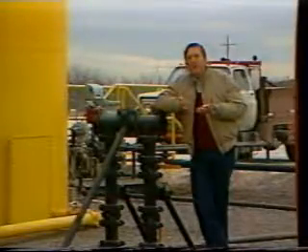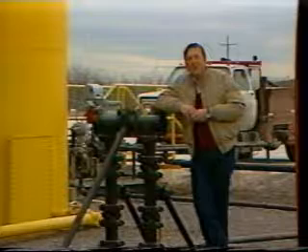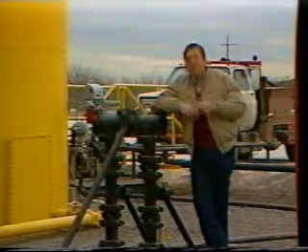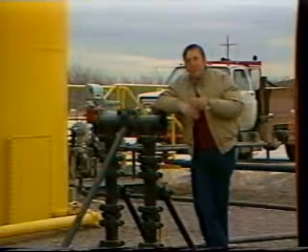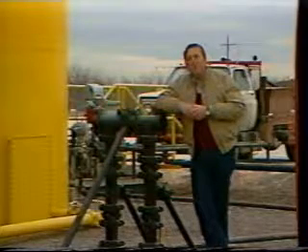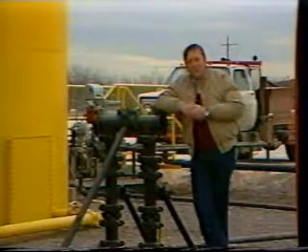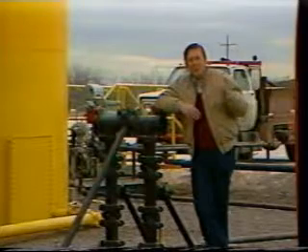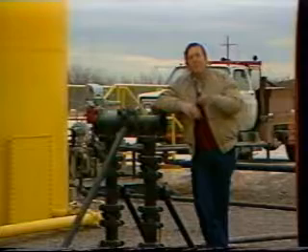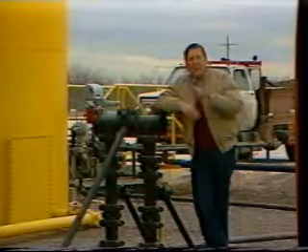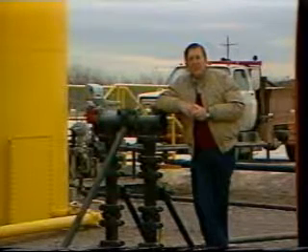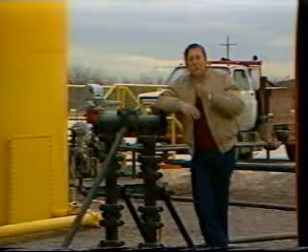We're here in Midland, Texas at a very colorful production facility, and here we'd like to show you how oil, gas, and water from producing wells are brought into this separation facility, how the oil, gas, and water are separated, how the oil goes into the tanks behind me, how the gas goes into a gas line where it's compressed and sent on to sale, how the oil is picked up by trucks, and how the water ultimately is disposed of in the water collection tank. Let's begin first then with the producing wells.